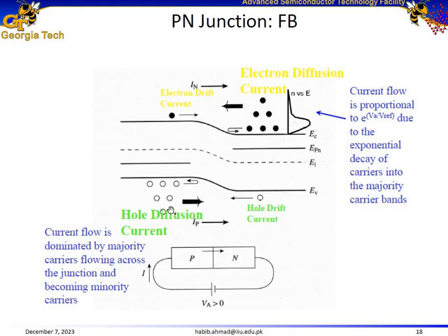depletion region, across the metallurgical junction. So under forward bias, it becomes easier for electrons to move towards the left, and it becomes easier for holes to move towards the right, towards the p-type layer, resulting in flow of carriers corresponding to a particular current in a p-n junction.